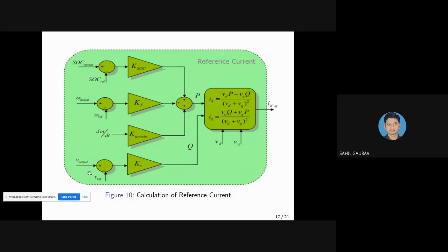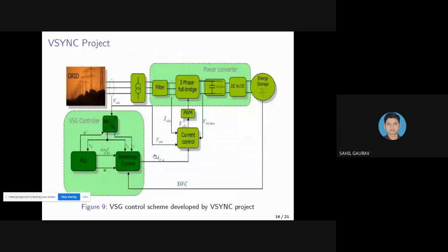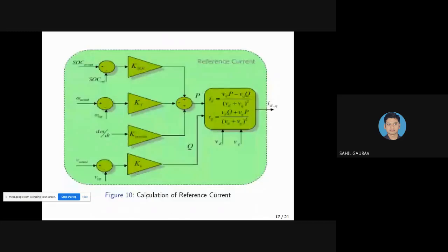Besides, this control scheme is not suitable for islanded operation without a voltage source, because, as I said earlier, this is a current source-based grid supporting control. So it requires other voltage supports to run in parallel.